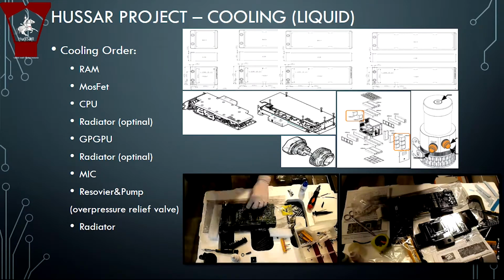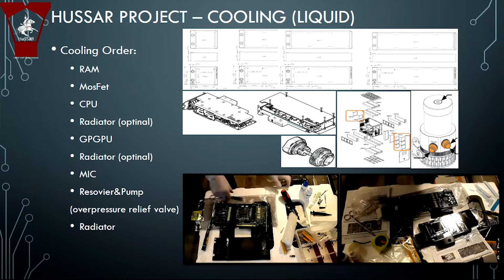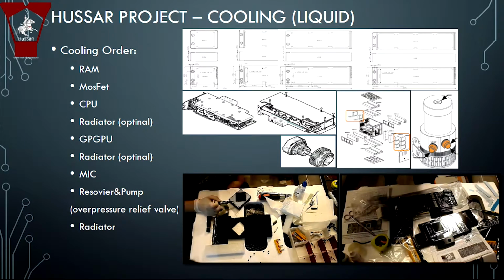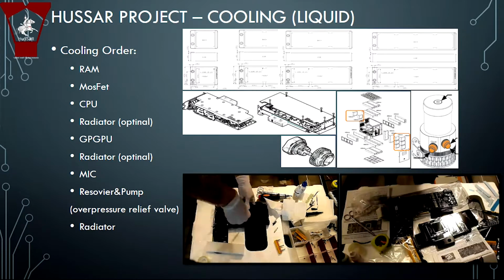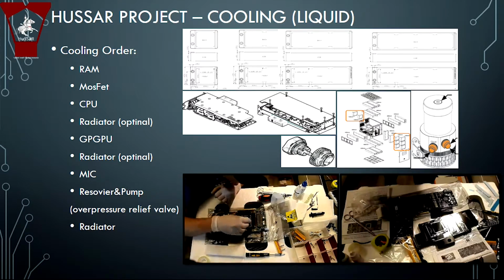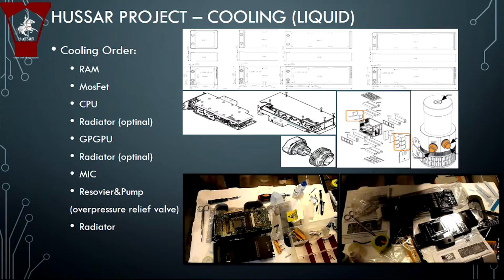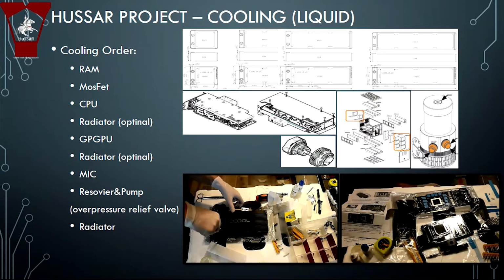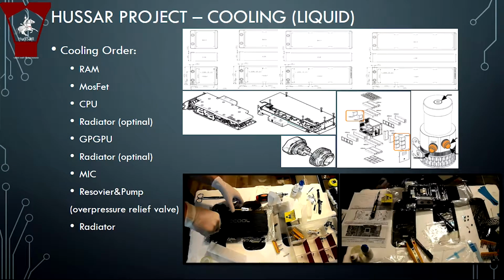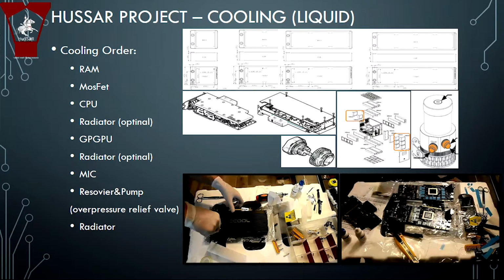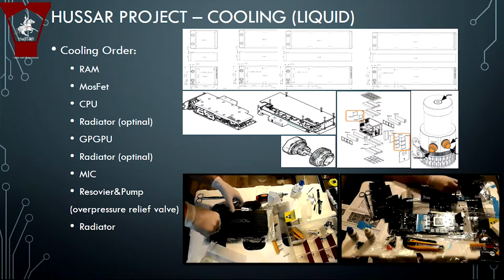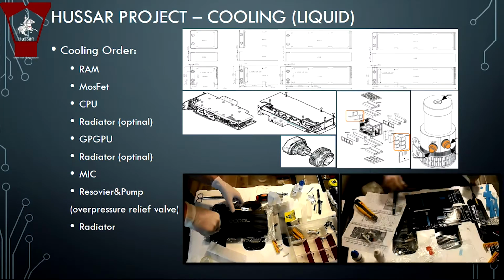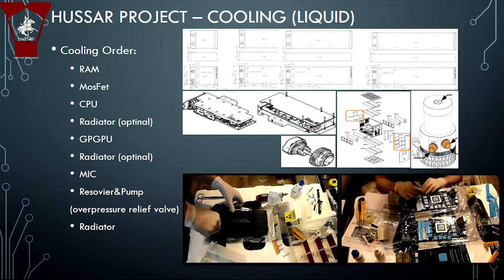because there is an overpressure relief valve on top. If the temperature is too high and the pump generates more pressure, it releases the overpressure. This is important because the cards can reach 90 degrees temperatures without any problem. So the liquid part is actually very similar to the cooling in the cars: there is a radiator, a reservoir, a pump, and an overpressure relief.